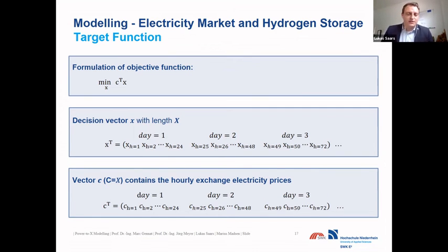Here you can see the 3 days, for example, with potentially 24 hours to refuel the storage. So each day therefore has 24 hours in which the hydrogen storage can potentially be refueled. And the aim is that the most favorable hours are chosen through the optimization. So to determine the cost optimal electrolyzer operation mode, the optimal electricity price forecast is needed, because you just have to know the prices in the future to do the kind of optimization we see on this slide.